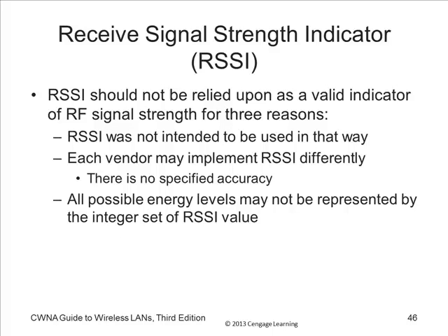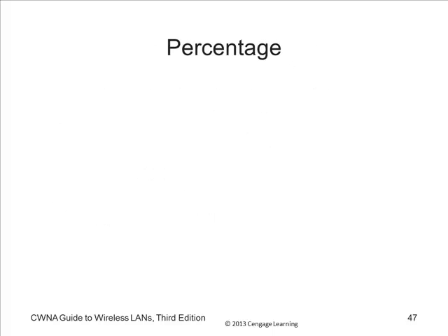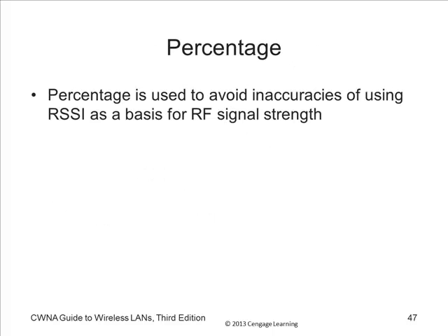See, MetaGeek actually has one that runs off a USB that's like $200. But it's only for a certain bandwidth, certain frequency level. If you want to do the 2.4 gigahertz, you can do that. If you want to do the 5 gigahertz, you've got to get a different one. So you've got to buy what you want. It's a lot cheaper than paying $10,000 or $40,000, but you've got to be careful as to what you're measuring. We have one, but it measures the wrong frequency. It doesn't go into the frequency that we want.